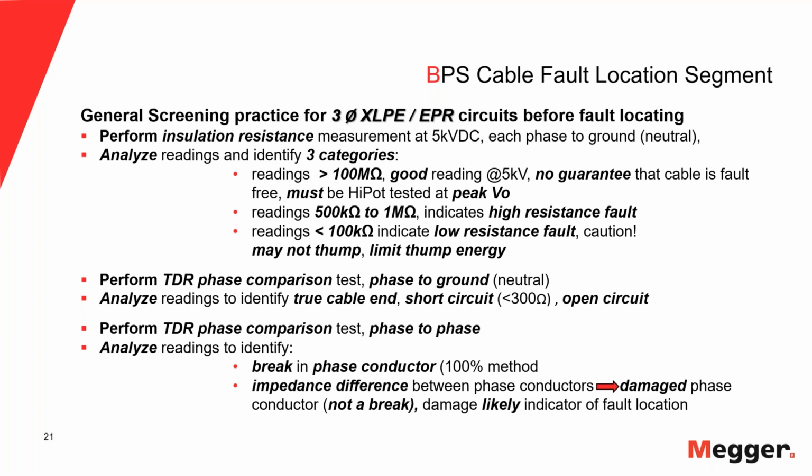They will find those, or they will indicate that I have that type of fault. But if I have an open conductor, and you will see there is one other test that we will do in a moment that will then close the loop. And with that test result in, I can make a final decision whether a cable is good or not. So it is several steps involved. Many times, somebody does an insulation resistance test and reading the sign says cable is good. Well, it might be, but it could also not be. And so be careful about this.